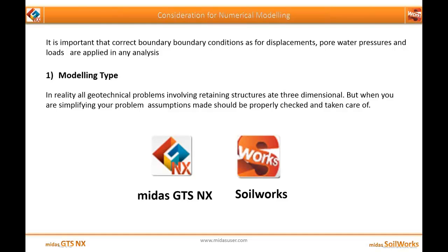Now, what are the various considerations one needs to consider while doing numerical modeling? First, it is important that the correct boundary conditions for displacement, pore water pressure and loads are applied in any analysis to ensure proper results and safety of the retaining wall or the shoring system. First of all, the modeling type. As we all know, in reality, all the geotechnical problems which involve retaining structures are three-dimensional. But when you are simplifying your problem, the assumptions made should be properly checked and taken care of.